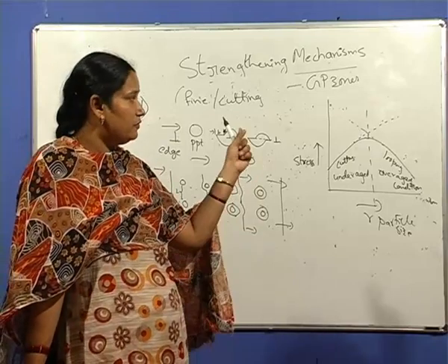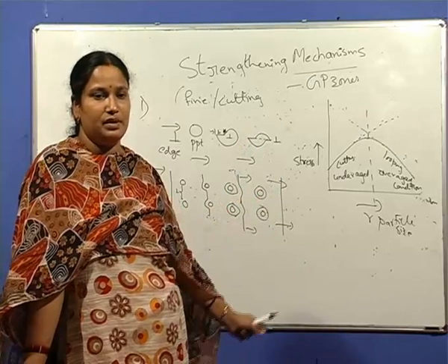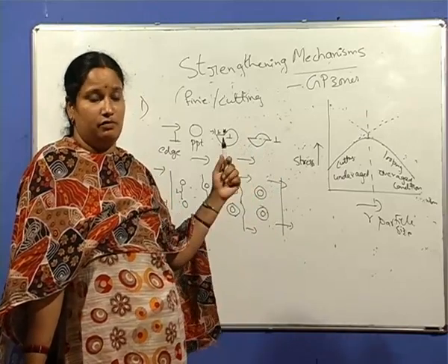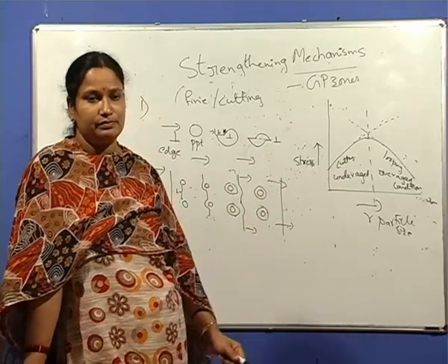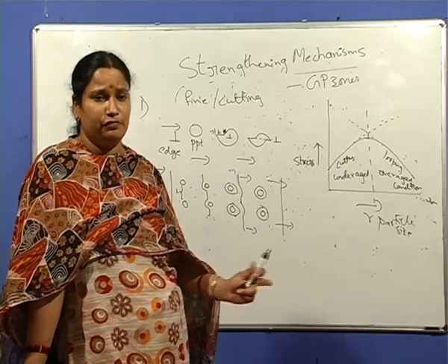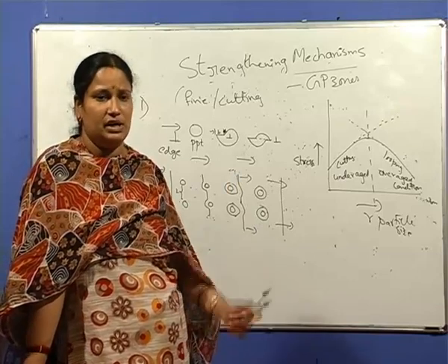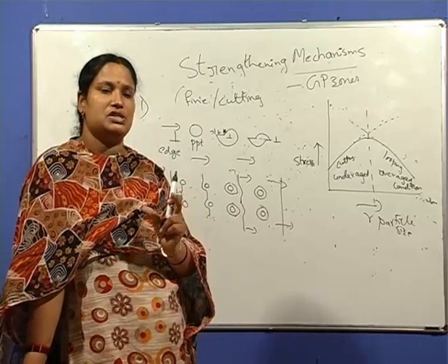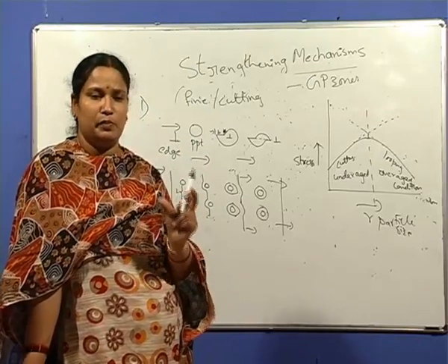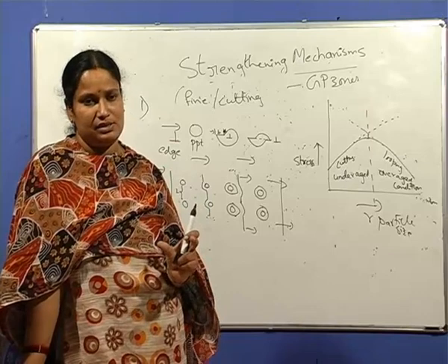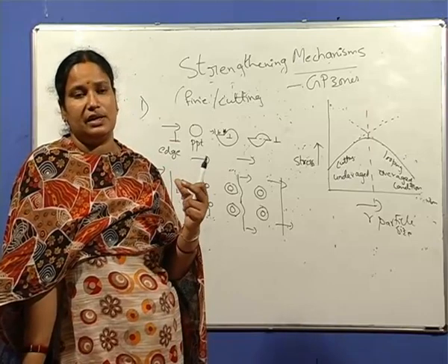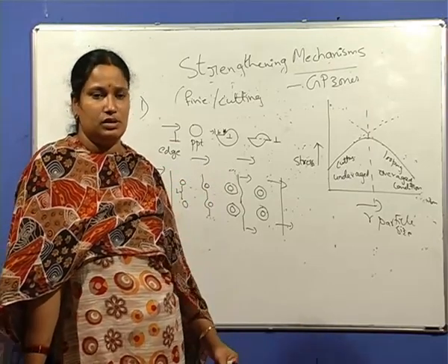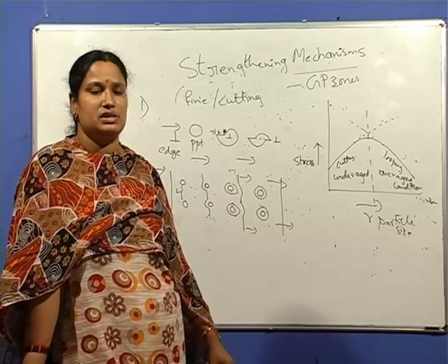For the aluminum copper alloy system, we have seen various transition phases that may not be found in all precipitation hardenable alloy systems. But one thing found in all of them is the formation of a coherent precipitate phase, and with still further increase in time, the coherency is lost and precipitate coarsening takes place.